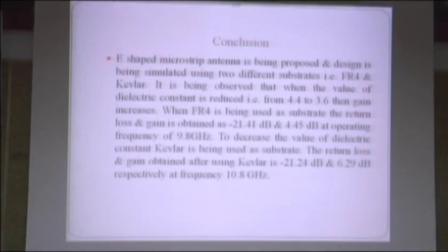This is the conclusion. If we are using FR4 epoxy or epoxy Kevlar, then FR4 epoxy has the dielectric constant 4.4 and epoxy Kevlar has 3.6. Then the gain increases when the dielectric constant is reduced.